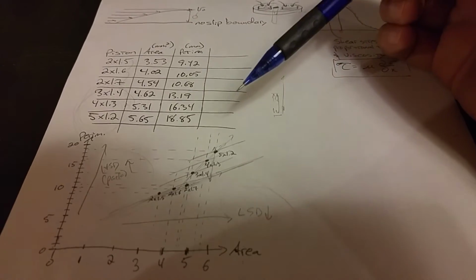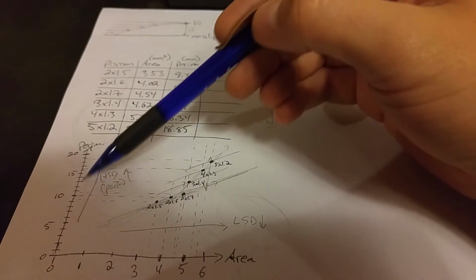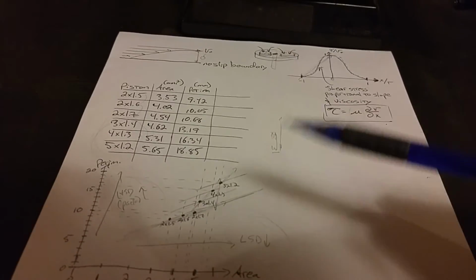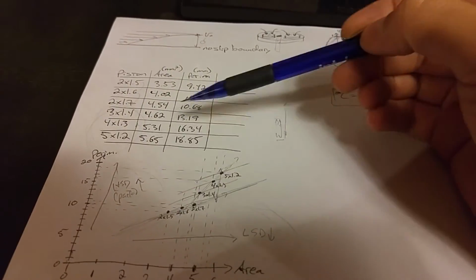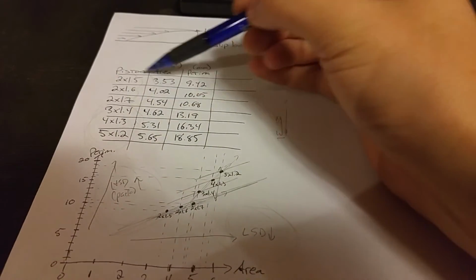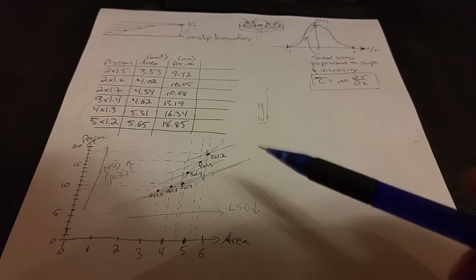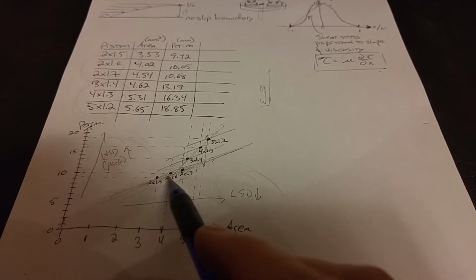But if I'm on an outdoor track that's very bumpy, then the high-speed damping is not just impacted by landing off of a jump, but it's also impacted by the car having to go over this really bumpy surface. So I might want to have less pack to allow the suspension to absorb all those high-speed bumps. So I would go to a 2-hole piston here, and within this 2-hole piston range there's not that much of a difference in pack.